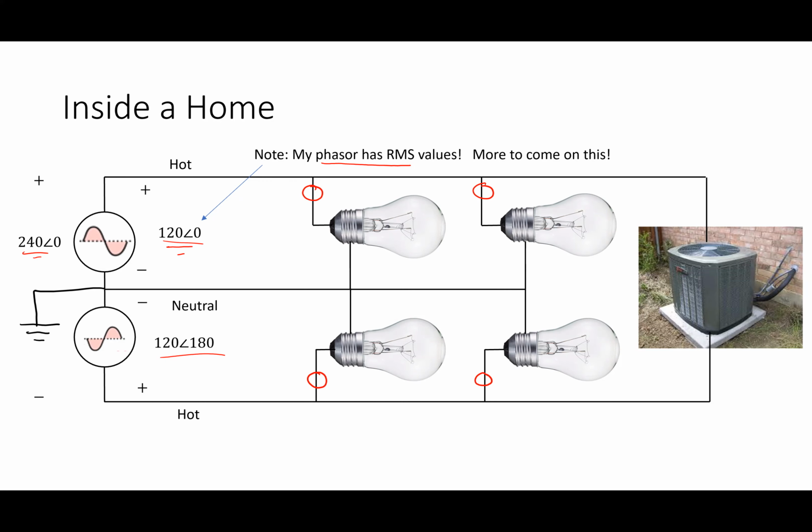Where's the power going in the dryer? The motor that spins the giant... not the motor. Yeah, that was a setup. It goes to the heating coil. The heating coil needs a lot of power, and it heats up that stuff. The motor doesn't. So in a washing machine, for instance, it usually doesn't have 240, because the motor in there doesn't take a whole lot. At least at home, motors don't require as much as the heating elements do. Okay, so we can talk about that kind of stuff for a while.